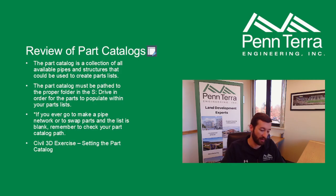Okay, so now getting into kind of the meat of things. We can't really talk about anything pipe network related without talking about part catalogs. So hopefully this is a bit of a review, but I think it's always a good thing to check anytime you're doing anything with these networks. So part catalog is a collection of all of the available pipes and structures that could be used to create a parts list. It has to be pathed to our S drive, or your parts list will show up as empty.